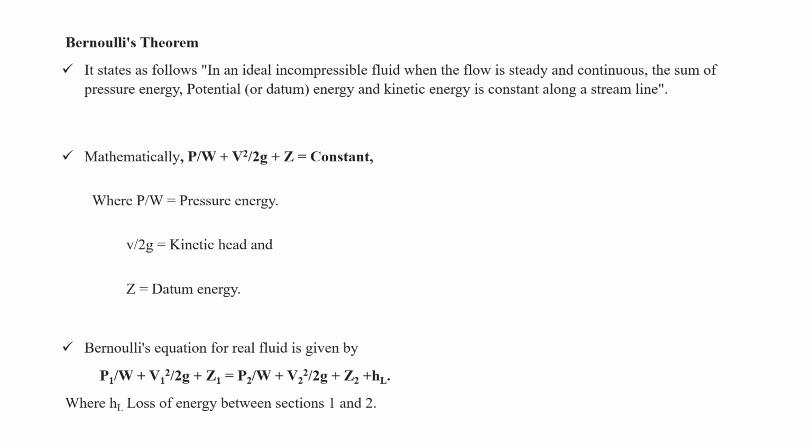Mathematically, it can be written as P by w, that is pressure energy, plus V square by 2g, that is kinetic energy or kinetic head, plus Z, that is called datum energy or potential energy.